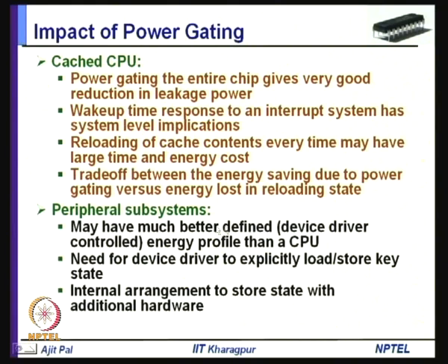Second is the peripheral subsystem. In this particular case the energy profile is much better defined than a CPU. Why is it much more well defined? The reason is, here you know that a particular peripheral can be a programmable I/O like a DMA controller, interrupt controller, or some other parallel programmable I/O, which are used in microprocessor and microcomputer based systems.